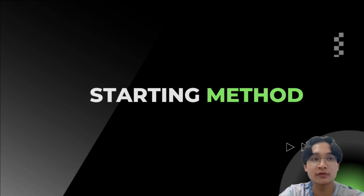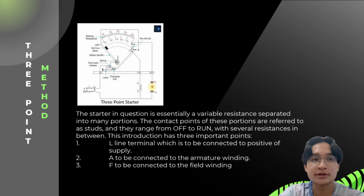Starting methods. The first one we have is the 3-point method. The starter in question is essentially a variable resistance separated into many portions. The contact points of these portions are referred to as studs, and they range from off to run, with several resistances in between. This starter has 3 important points. The first one is L, the line terminal, which is to be connected to the positive of the supply. The second one, A, is to be connected to the armature winding, and F needs to be connected to the field winding.